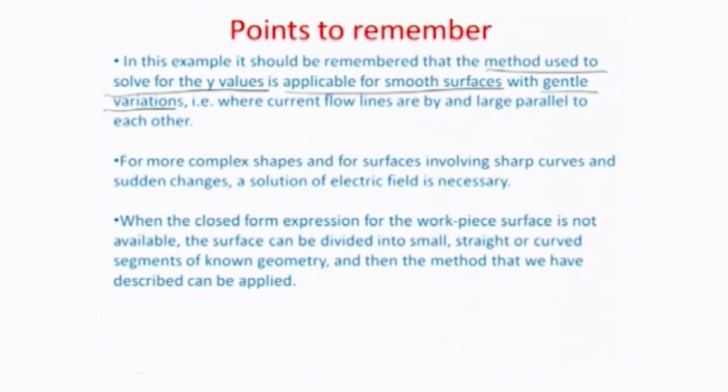One of the reasons why smooth surfaces are the point of discussion here is that if the surface is too rough, then there would be a local variation of the electric field, and in the approach, or the algorithm, we have developed, that variation of the electric field is not accommodated. We still assume the electric field to be constant, depending on the function of the inter-electrode gap.